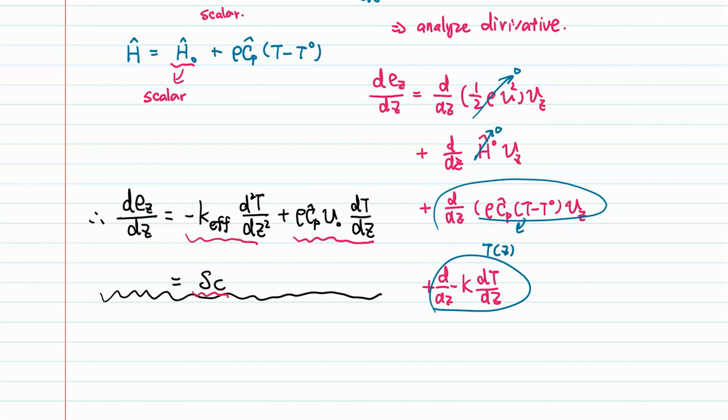Okay, so to continue our discussion, we're going to discuss the problem from zone to zone. So we have 3 zones, right? Zone 1 and Zone 3 are the inert zones, and Zone 2 is the zone that has the catalyst where the chemical reaction occurs. So if you look at our final equation, in Zone 1 and Zone 3, there are no chemical reactions.